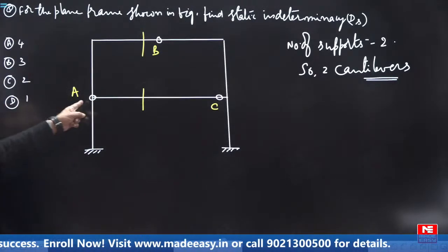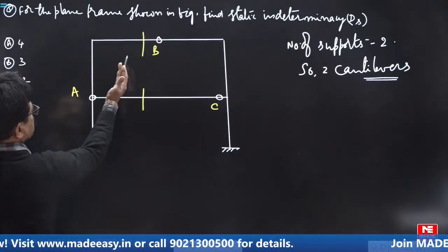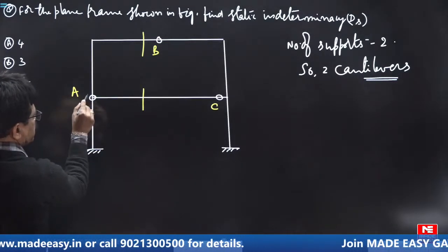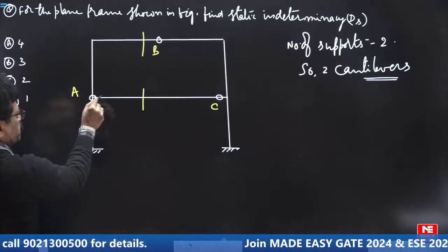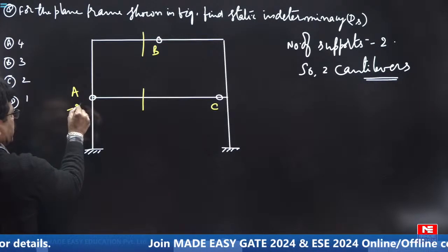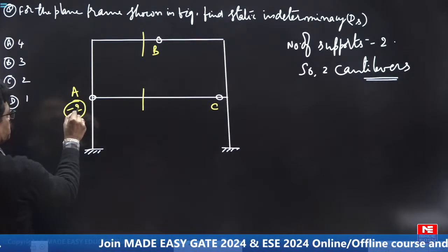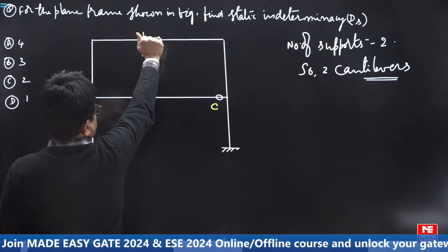Now if you have a hinge at the joint itself, it is not a stable cantilever, so you have to make it rigid jointed one. So if you add 2 moments, third moment is sum of the above 2 only. So unnecessarily you are adding 2 reactions, so subtract 2. Now after cutting it, it will rotate, so fix it.